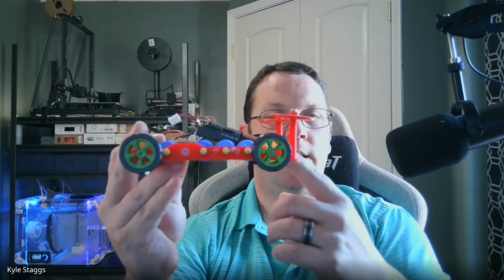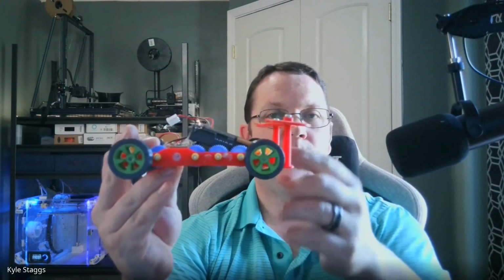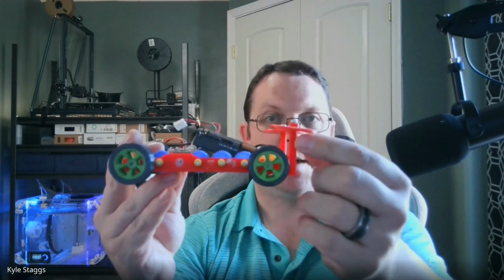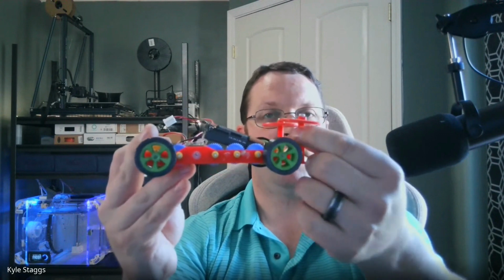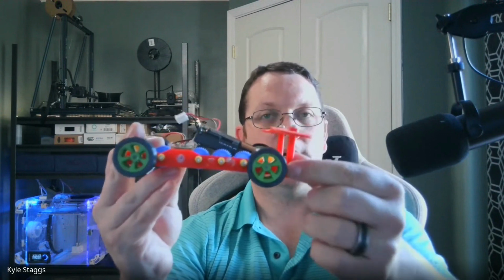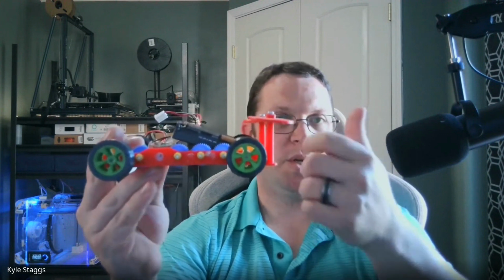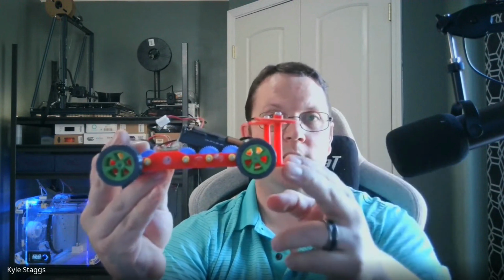Not only will that not have a high degree of success in terms of printing accurately, that millimeter shaft has no strength and rigidity. You need to have a minimum, absolute minimum of about 4 millimeters thickness on that post in order for it to have a chance of surviving both the printing and construction processes, let alone the actual race itself.